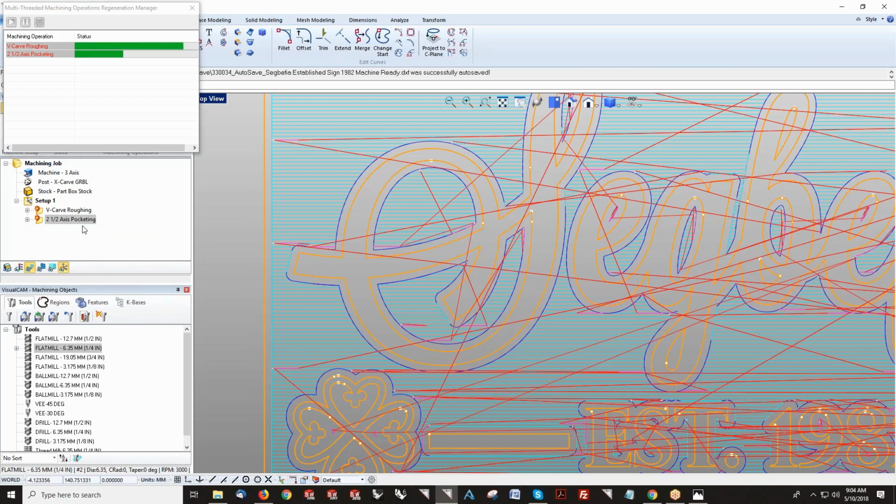I'm not sure exactly, because in the VCarve roughing we can compute it based on the tool's draft angle, because as you cut deeper, the offset keeps increasing. That's the beauty of V-carving, it can automatically account for that. So the first level at 2 millimeters has a different offset compared to the next level, and that is automatically computed in the V-carving operation.